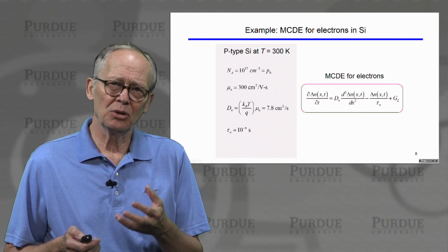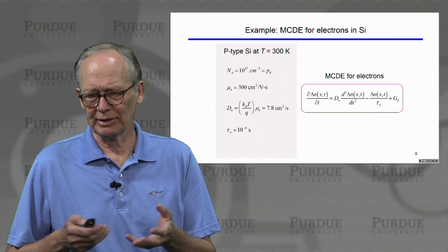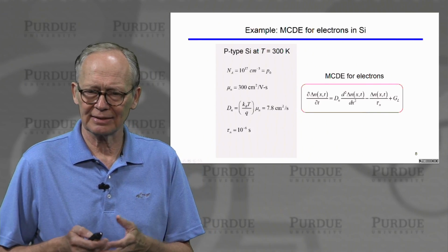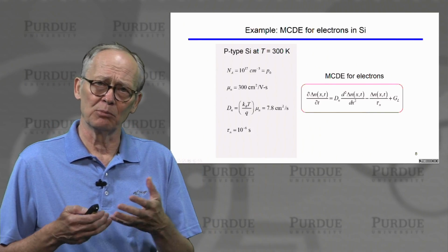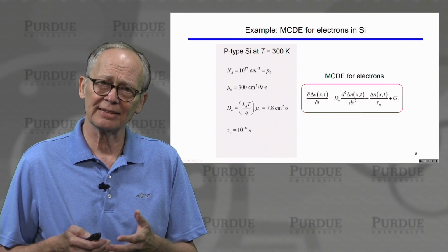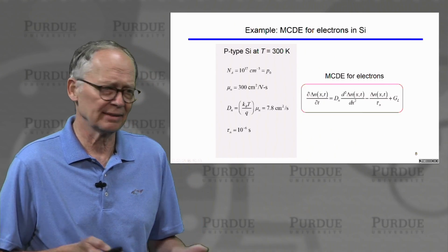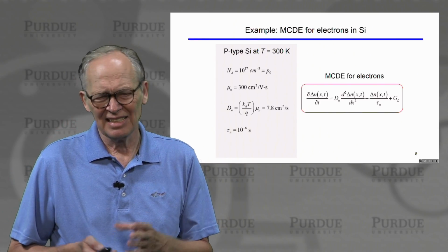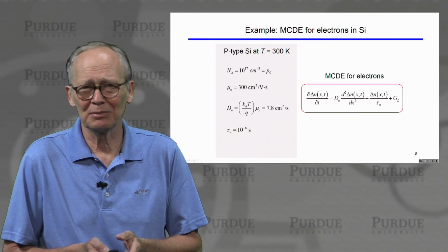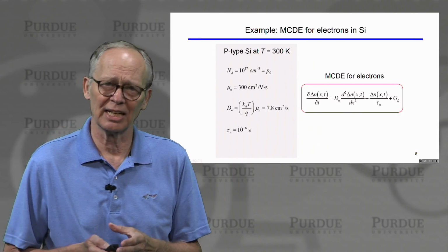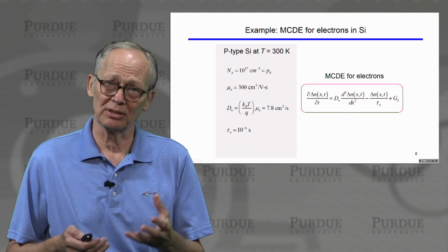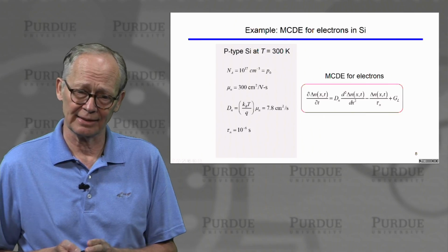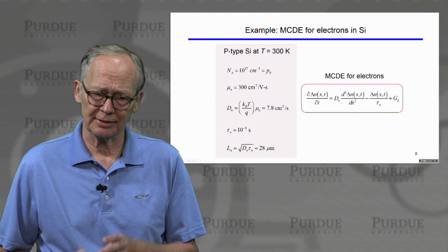We will need to know the minority carrier lifetime, whether it's due to Shockley-Read-Hall processes or whatever. In this case, it would most likely be defect-assisted Shockley-Read-Hall processes, and I'll assume that the minority carrier lifetime is 1 microsecond. That's not an extremely short time. It's also not an extremely long time. It's possible actually to get millisecond lifetimes in high-quality crystalline silicon.